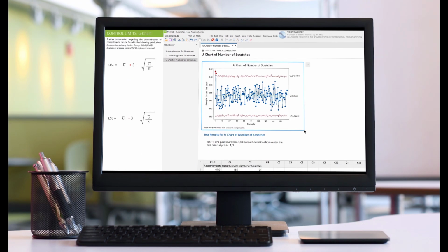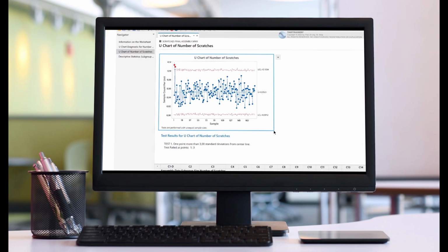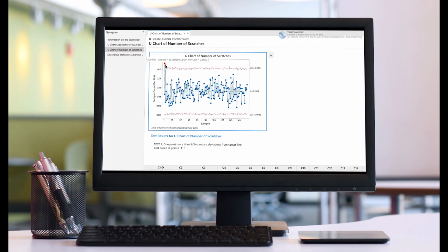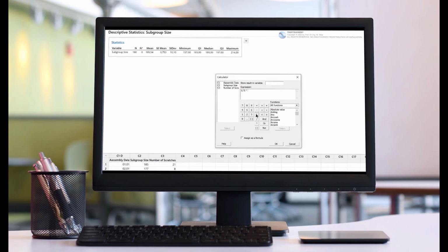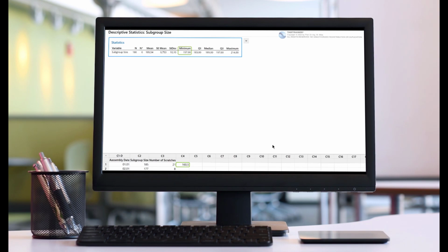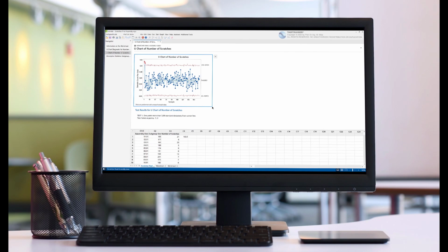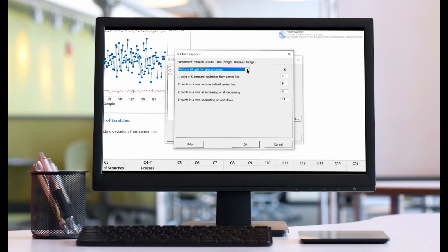The central learning objective is to map the frequency of events, in our case the number of scratches on the skateboards, by using a corresponding quality control chart, and to analyze the assembly process with regard to its process stability. In this context, we will get to know the so-called U-chart and C-chart, and learn how we can use a corresponding U-chart diagnosis to check whether the scattering behavior of our data set also follows the laws of Poisson distribution sufficiently well. We will also understand how we can manually estimate the corresponding control limits according to the AIAG standard